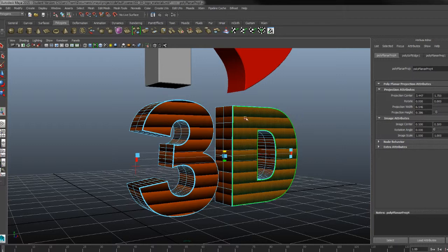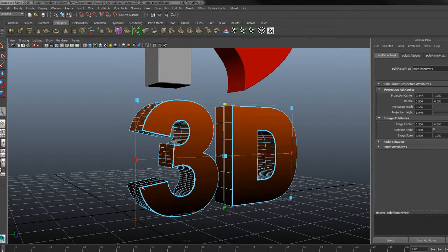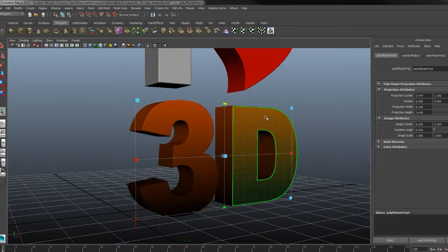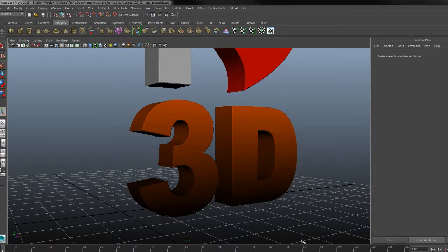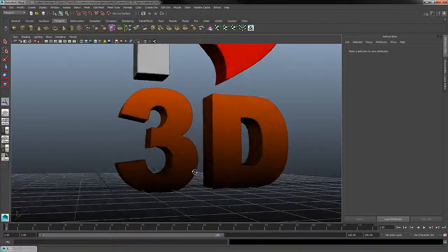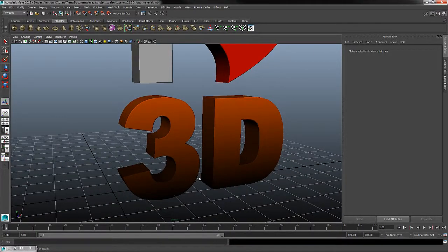So if I wanted to tile, you can see my ramp is repeated several times. We're going to keep it at the default. I'm not going to touch this gizmo at all. As soon as I apply it, I'm going to right click on the object and go to object mode. All that does is complete the operation, and then I'll click away from the object to finish that. So see how this applied proper UVs.